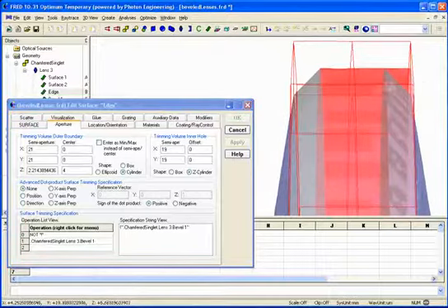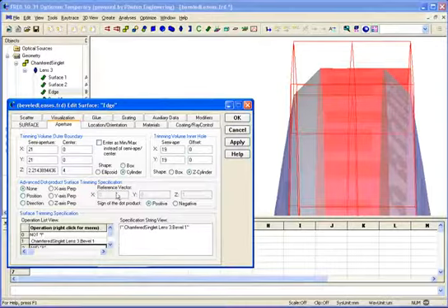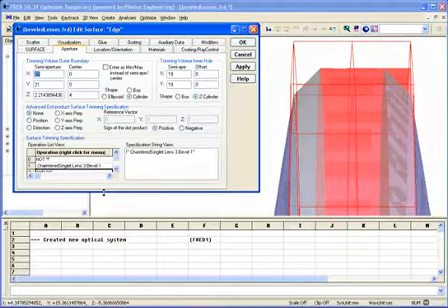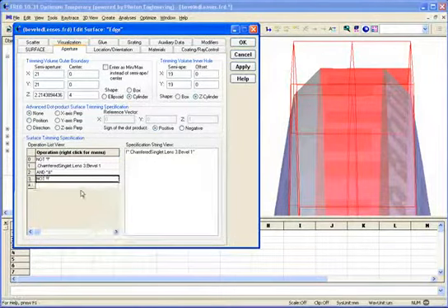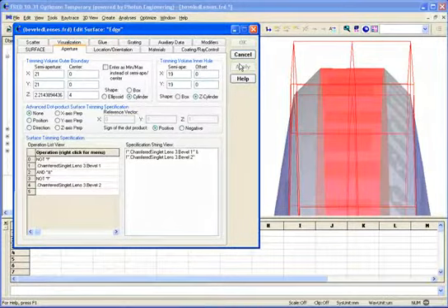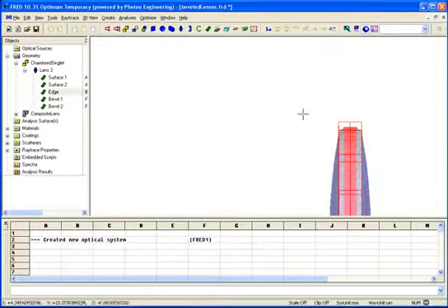I need to do the similar operation for the second bevel surface. Remember, pointing inward for the cylinder. So now the Z positive lies to the left, so I need to trim away everything that's not in the Z positive direction. So I'm going to, let me move this up. Not, select entity, bevel 2, hit apply. And now I have a simple chamfered singlet.